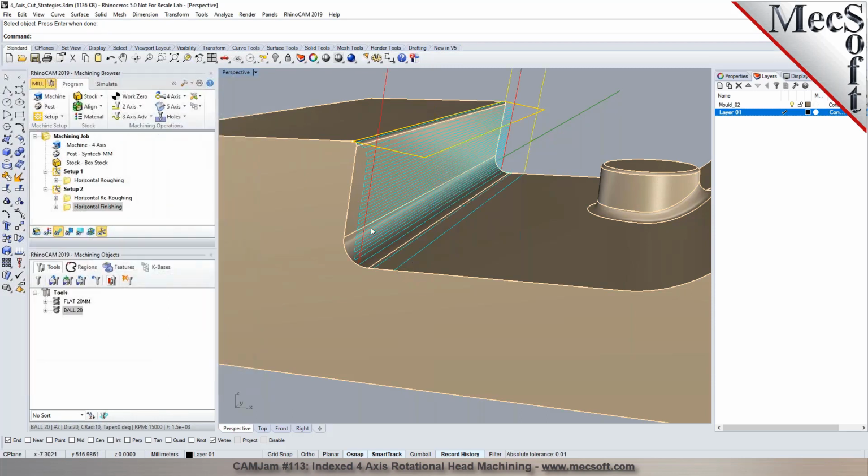So one of the things I could do, just to finish these radii, is a between curve machining. So I'm going to extract these 2 curve edges in here. And now those between curves, is it either side of the curve or is it actually up to the tip of the tool? The tool tip is going to stay upright up to this area, so I'm going to use a gumball to move it out by like 10 millimeters. And we'll check the direction of these 2 curves, make sure they're flowing in the same direction.